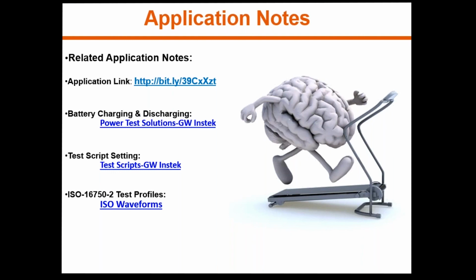So you can put in, for example, a zero DC voltage and create, if you're familiar with halfway rectified waveforms, where you're only taking half of the waveform and it skips a cycle or half cycle, right? And it goes up to it, so you have that peak. You can create that. So you're implementing an AC component, which is a sinusoidal component, and a DC component, which is just the straight top of voltage. Yes, that's good.